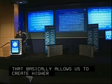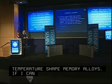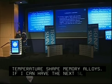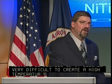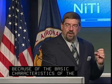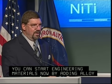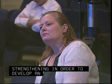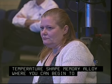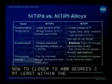If I could have the next slide. What we've basically found out from all this work is that once you get above about 300 degrees C, it becomes very difficult to create a high temperature shape memory alloy because of the basic characteristics of the individual phases. But there are things that you can do. You can start engineering materials by adding alloying additions, using solid solution strengthening and precipitate strengthening, to develop an engineered high temperature shape memory alloy where you can begin to push the usefulness of these materials closer to 400 degrees C, at least within the systems that we're working with. If I can have the next slide.